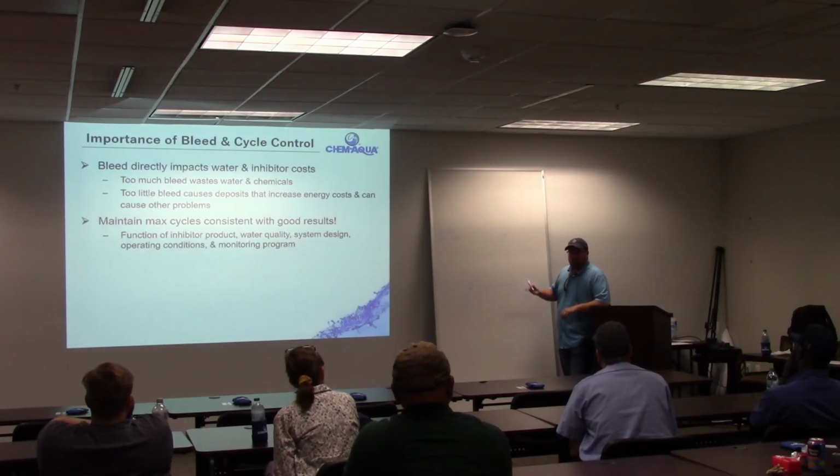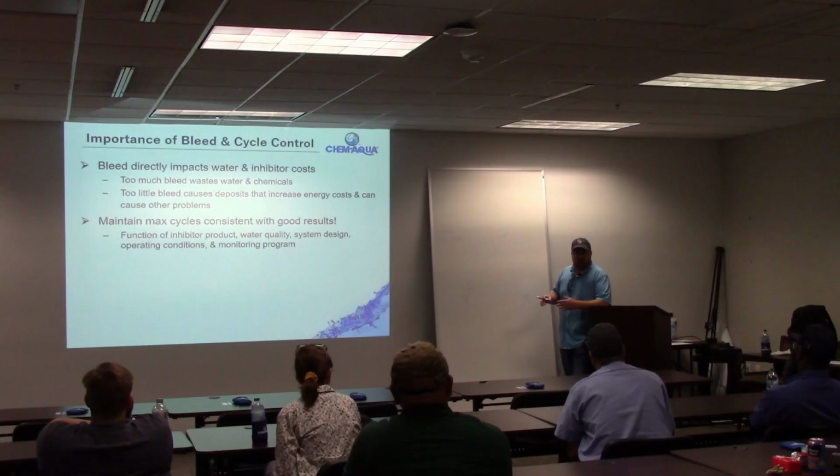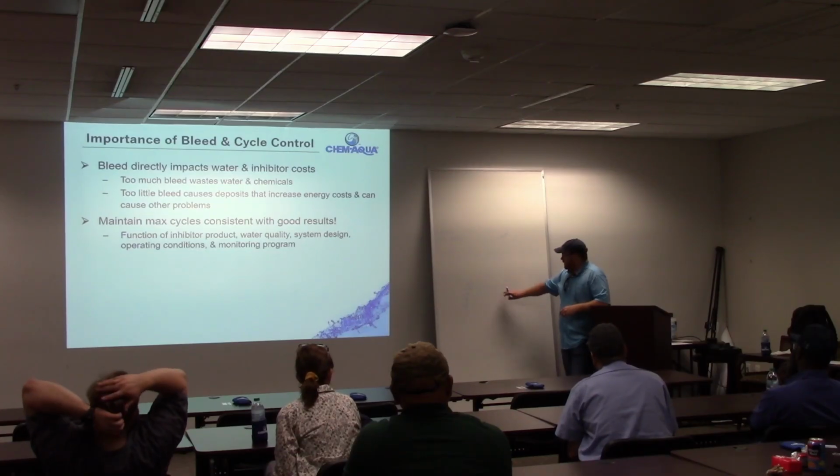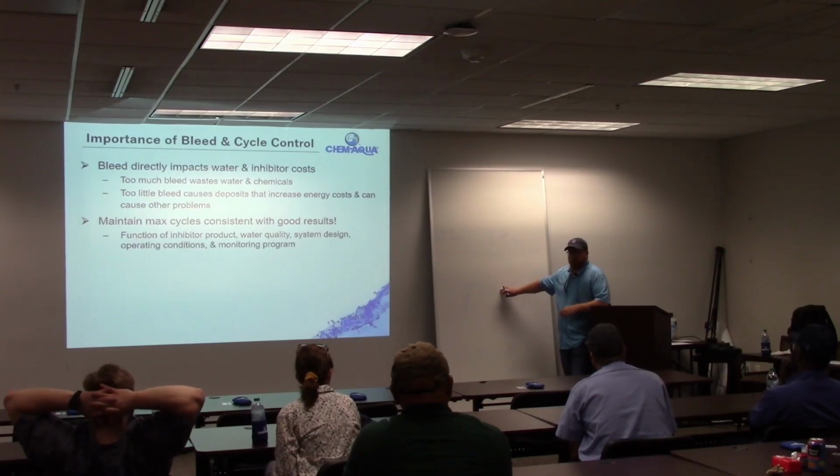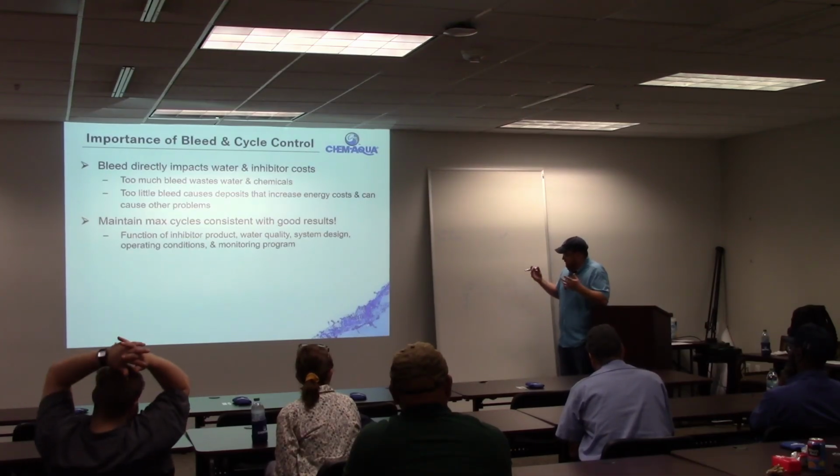At some point, depending on the water chemistry, the type of chemical that you're feeding and everything like that, you're no longer going to be able to keep all those marbles dissolved, and they're going to start precipitating out as scale on your tubes. That's how we choose a conductivity set point, and this is what cycles is, all right?